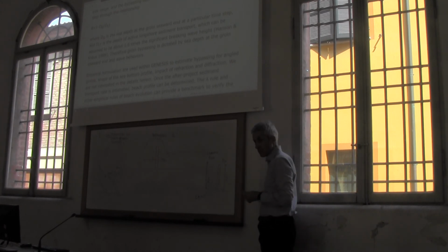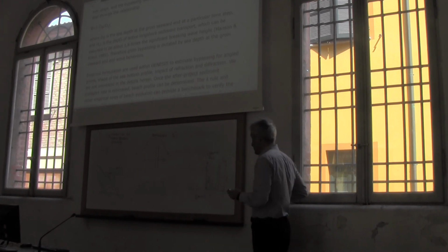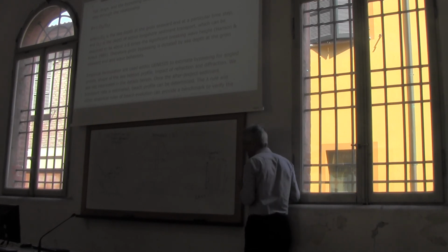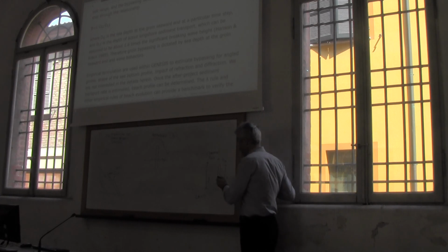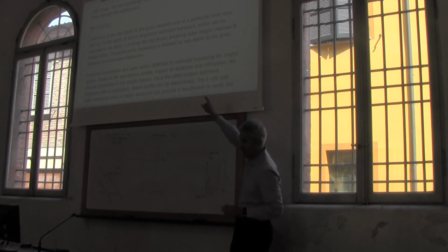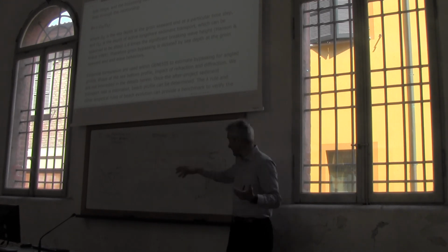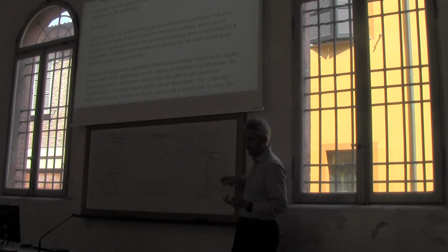If the groin is short, the depth of the groin will be lower. If I want to increase the length of the groin, I need to increase the depth of the groin at the end. Now, what does it mean if DLT is equivalent to DG? It means that the length of the groin is the same as the length of the active zone. So using the ratio of the depths is just another way of using the ratio of the length of the active zone and the groin.